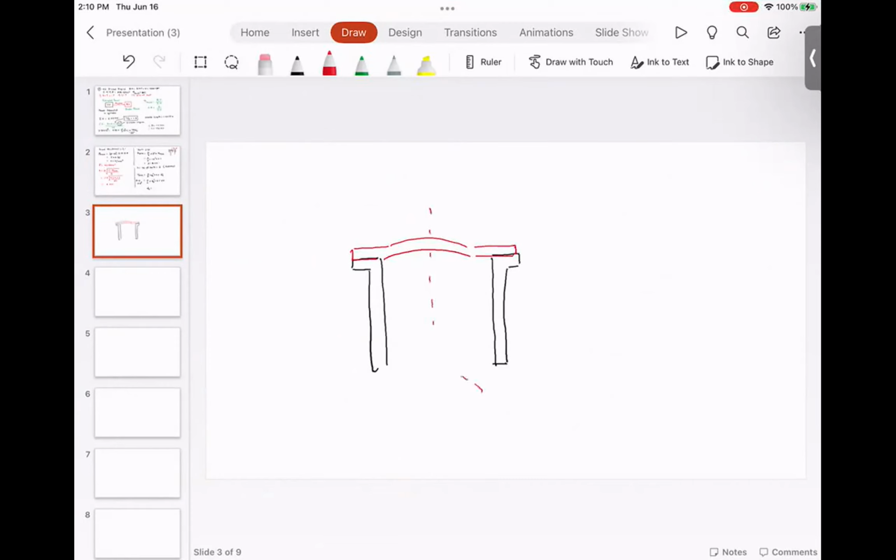If you look at the top view, the bolts have two purposes. The first purpose is to ensure that the cylinder head stays attached to the cylinder. Also, the other purpose is that this joint is leak proof.